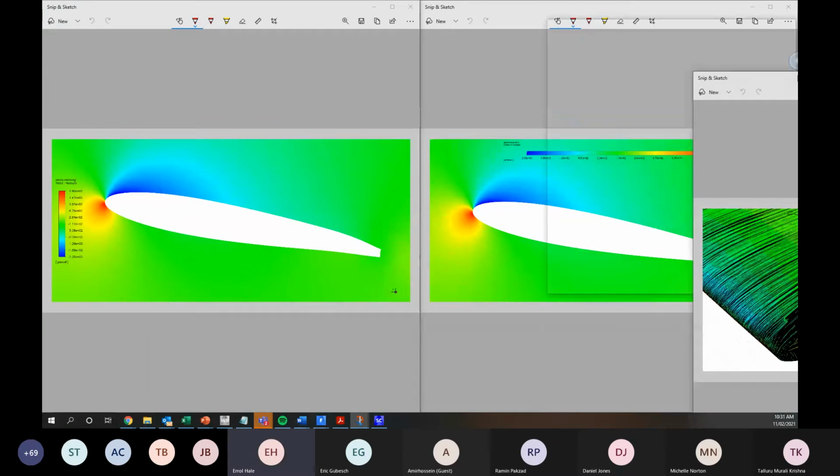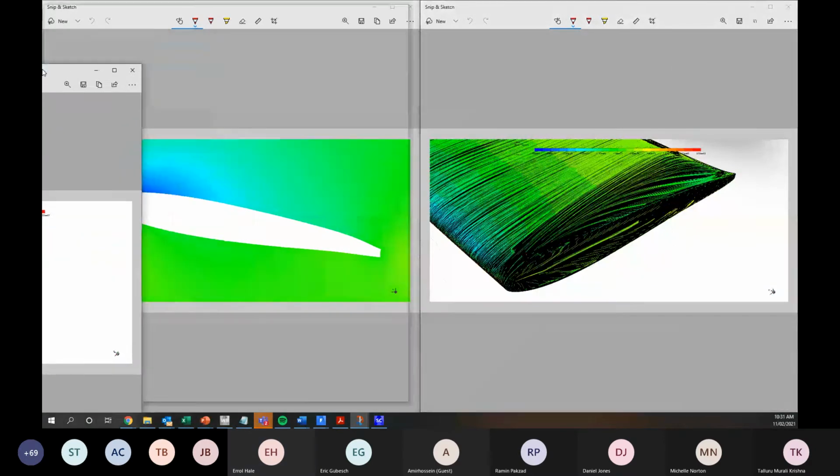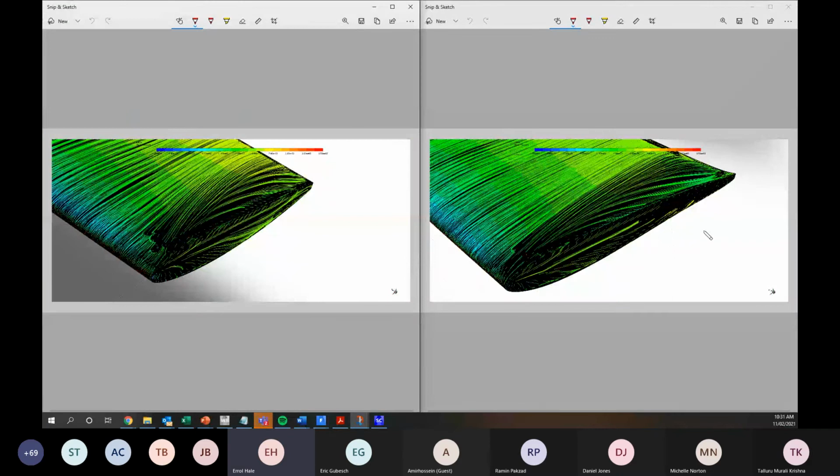Taking an oil flow. So it's a really cool way of getting an optimized shape. This increased the thrust by over 30% and increased the lift over drag by over 15%. Okay, and that was without getting to the absolute maximum that we could have for those simulations.